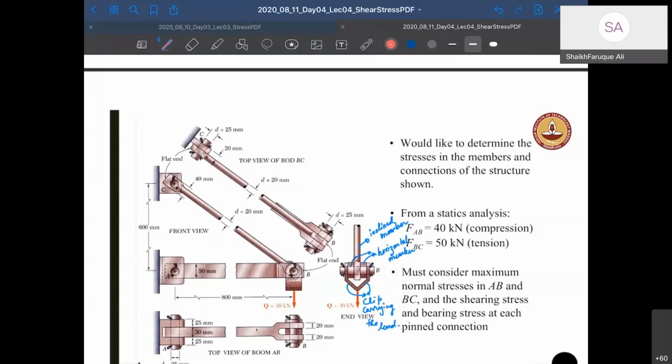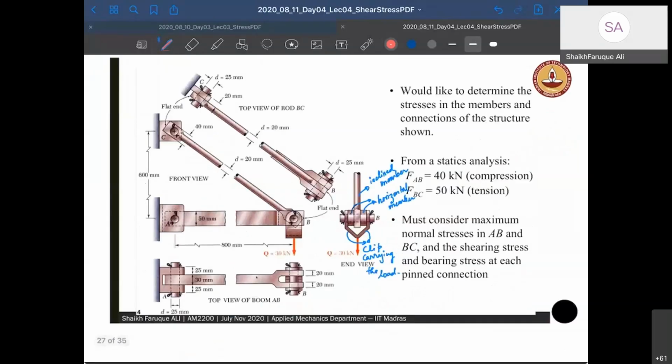For example, concrete will have almost zero in tensile. So you cannot allow any tension in concrete. And in compression, it will be 25 MPa, 40 MPa, 35 MPa, given the conditions. But tensile, all of them will be assumed to be zero. So you cannot give any tension in concrete. It will be only for compression. So you have to check both tensile and compression. Right, Jai, please check it. It's not difficult to do.